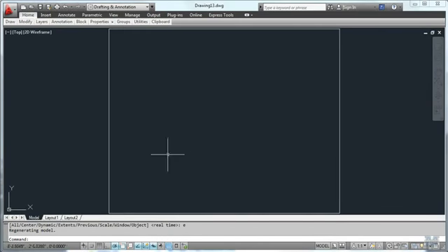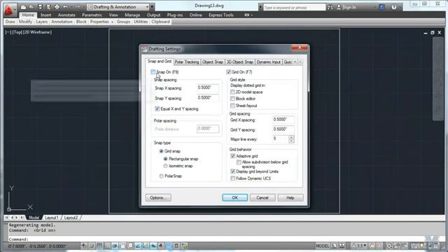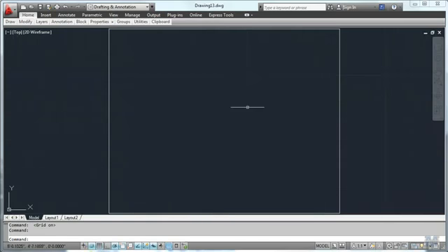I think I'll also go ahead and turn the grid on. That's down here. It's the F7 key as well. And then I right click settings. I know that pops off the screen, but I've got the grid on. Let's do the snap on, 1/2 inch by 1/2 inch, and put major lines every 12. That way I'll see every 6 inches on the grid. So there it is. And then we're going to go ahead and draw.